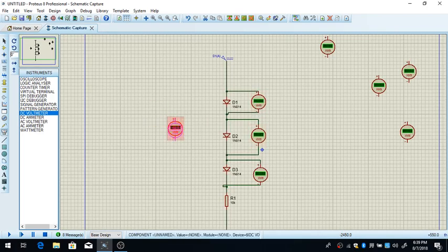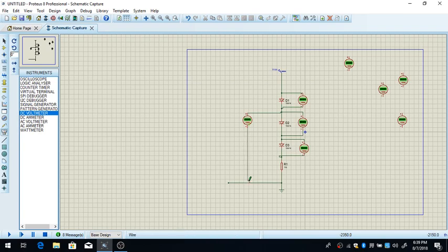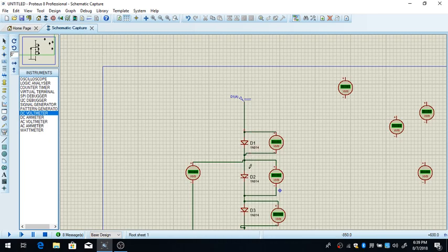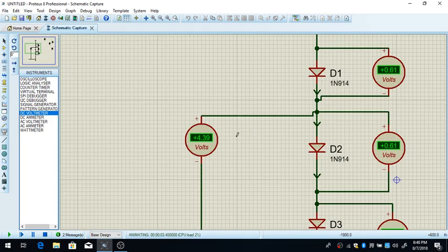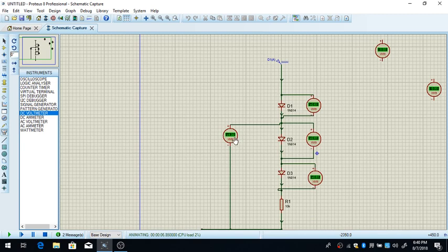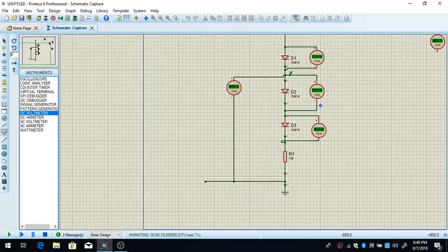So for example, if I measure here the voltage in reference to the ground, it will be about 4.39 volts, the potential difference between this and this. When I run the simulation of the electrical schematic circuit, you'll see that here we have 0.39 volts, because here we have 5 volts minus this 0.61. Therefore we have 4.39 volts potential. Here on the ground we have 0 volts. The voltage is this minus this, and that's 4.39 volts.